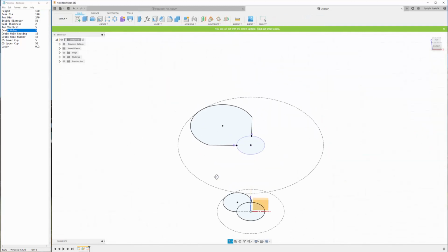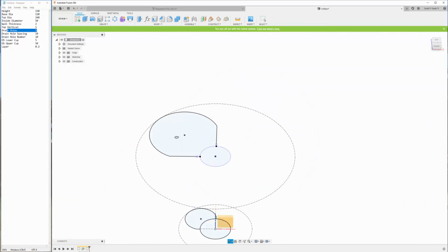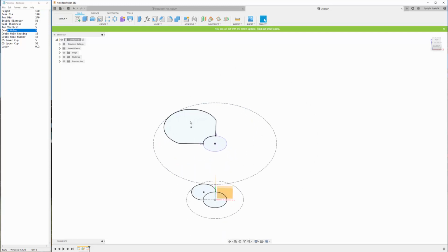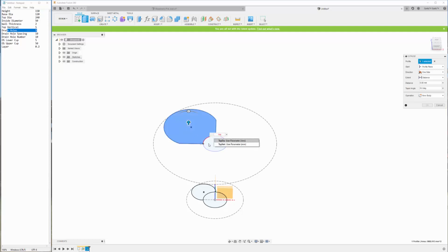So now if I look at it, I have my two sketches, my upper and my lower. Because I defined my whole object as being 150 mil high, I actually want the 5 mil vertical to be down from that surface rather than up. So I can select this and hit E for extrude, and then go minus the top vertical distance. So there's our 5 mil.